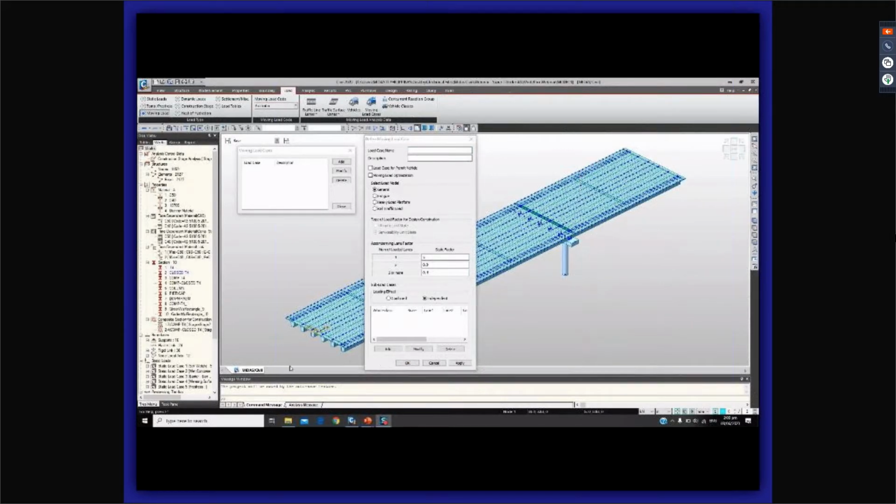So the program just ought to see our moving loads. Going back to moving loads, it could identify this as a load case for a permit vehicle, or if you use moving load optimization, but use Girder Bridge Wizard, not optimize. It can also modify its general load model, fatigue load model, heavy load platform model, or real traffic load model. So the combination for different moving loads will be different. So just identify it as general.